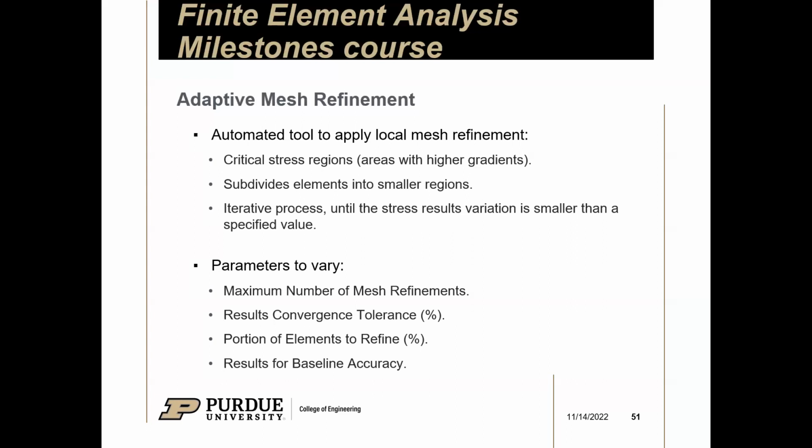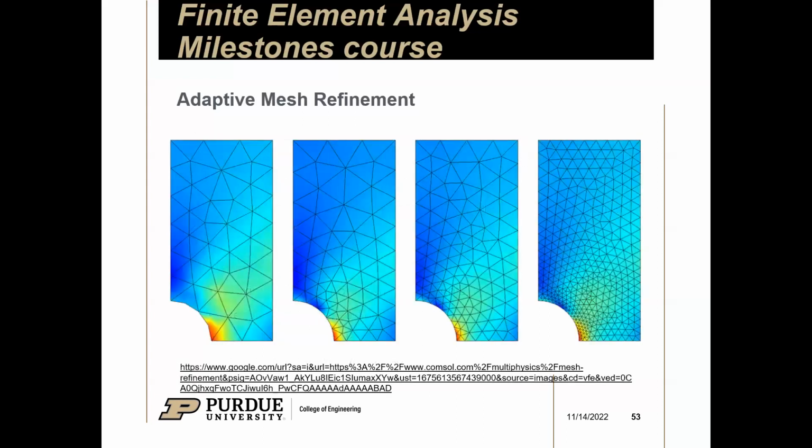So let's go. This is a visual representation of what adaptive mesh refinement actually does. You can see from the leftmost to the second leftmost, at that point where that crack is, where that red area is, the mesh actually got a lot more accurate. But look at the top left, the triangles didn't really change in size, right? So that's what the system means.